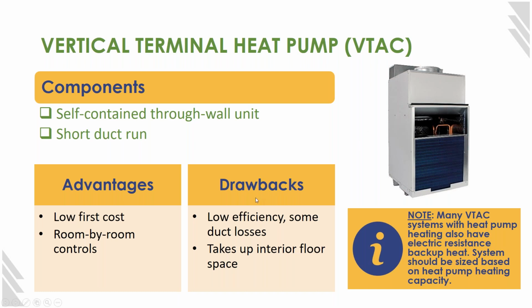Some of the drawbacks to these, they also, like PTHPs, tend to be fairly low efficiency heat pumps. And because you have some ducting, you do get some duct losses. And they also take up interior floor space. This is a unit that goes through the wall, extends into the room, and they're usually put into a closet. There's like a sort of framed out area that these are enclosed in.